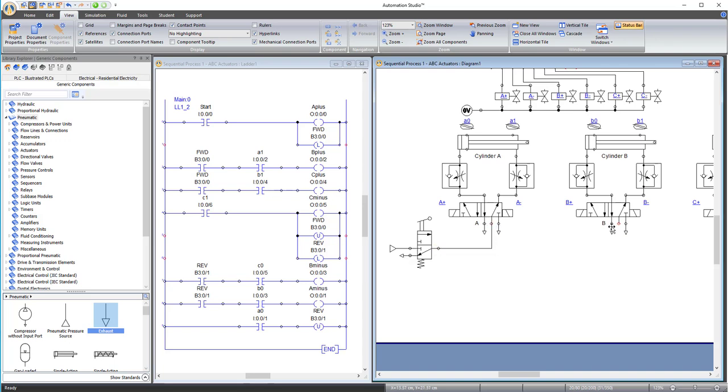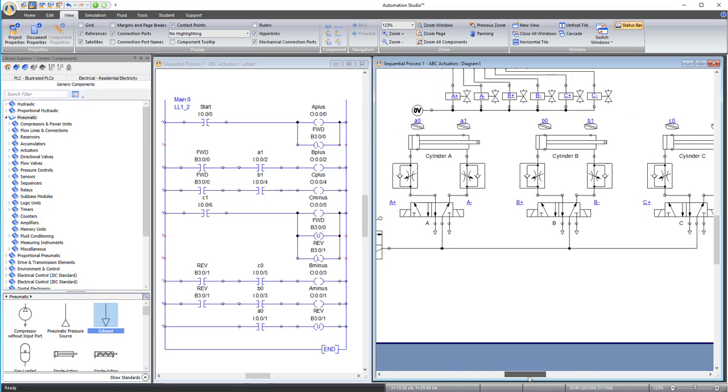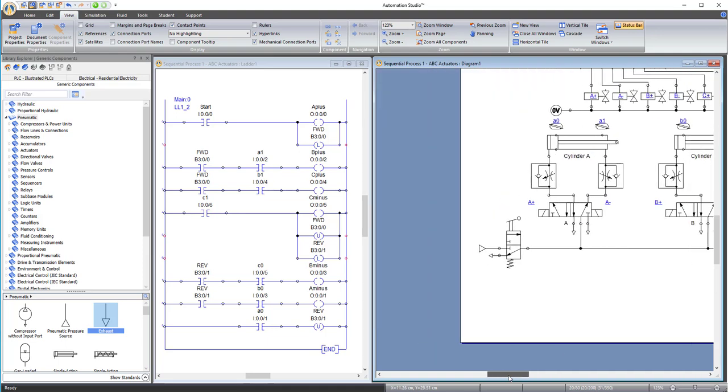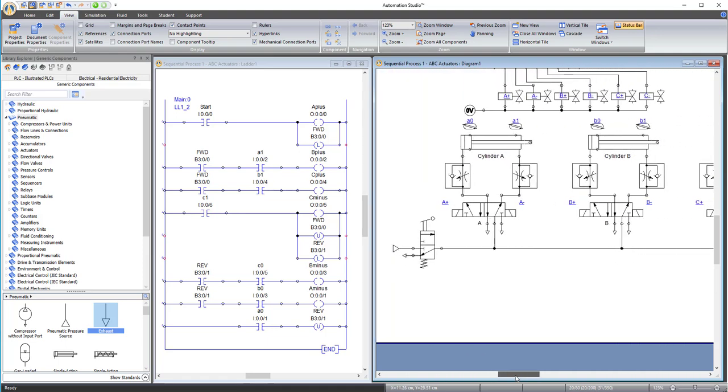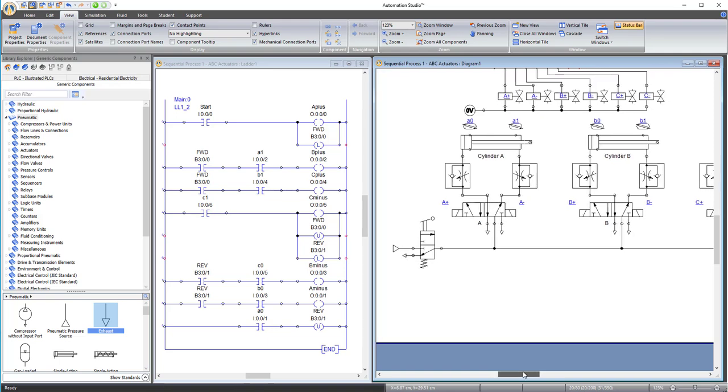And I'm just going to connect this up to the 3 control valves. So this is kind of like on the HAS 200, the valve manifold, which has all the valves in one place, have one common pneumatic pressure source, and there's a little valve on each station that opens and closes to allow the air to flow in.